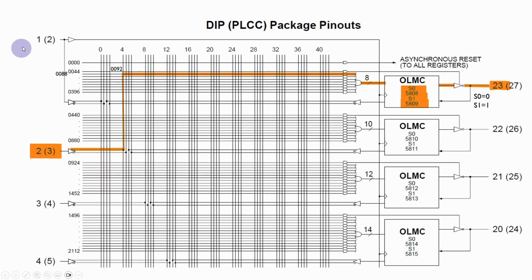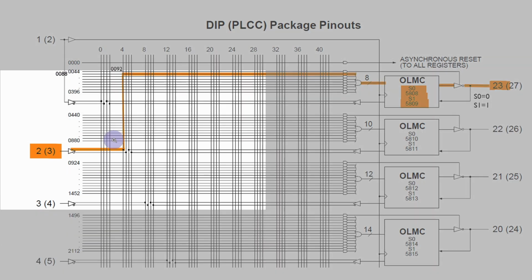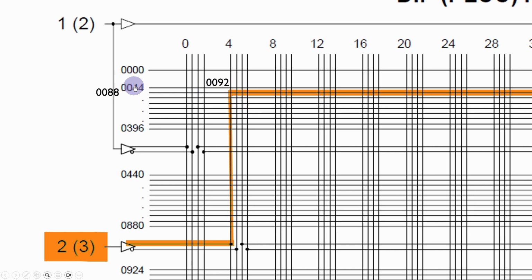So what I've done here is I've taken an extract of this and I've worked it through. So what this actually shows, if fuse 92 is in fact the second line down here, if I just zoom in here, probably make it a little bit easier to see. So you can see here the first line is 44, there's 44 on each row, so the next one is 88, and in fact this is 88, 89, 90, 91. So this first one here is 92. And we can see that in fact this shows the route for pin 2 taking the normal logic, so this is not inverted, going straight along there, and then it's...